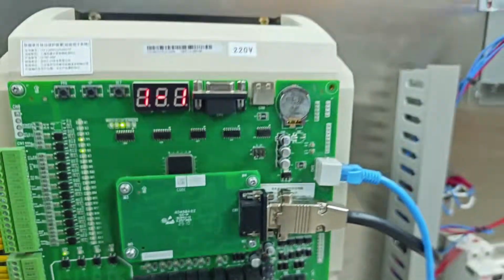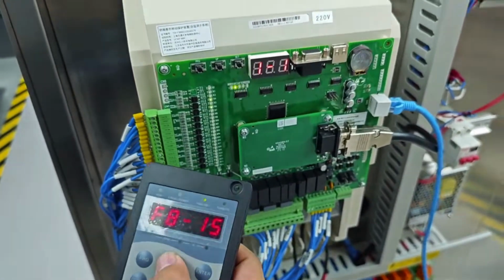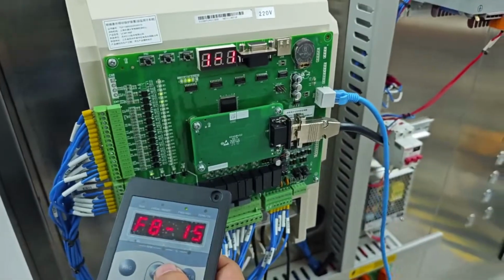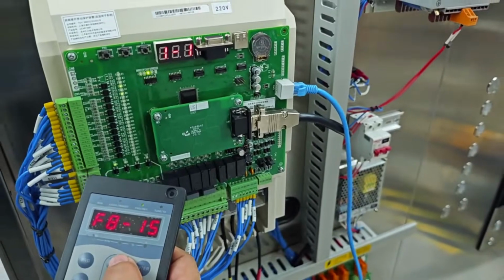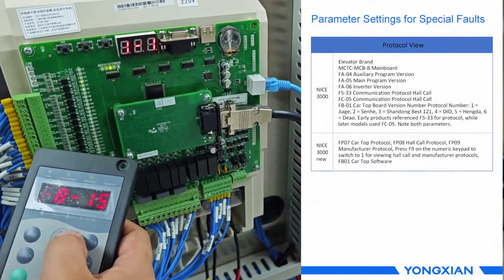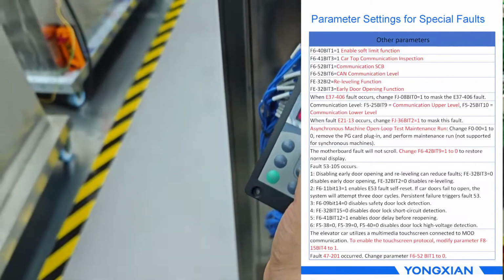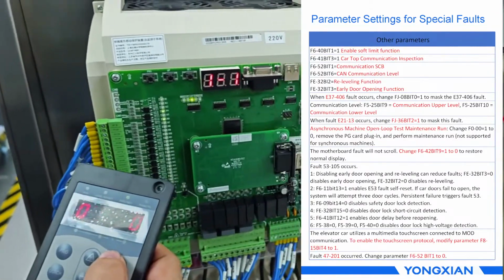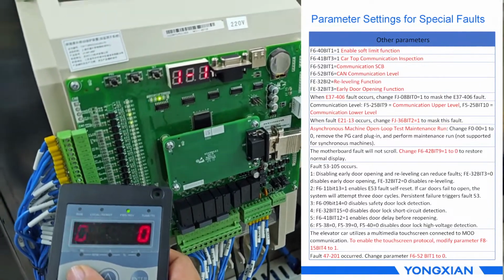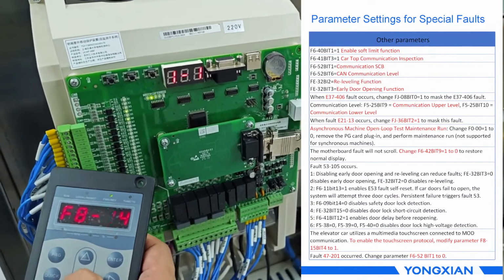If the elevator car has a multimedia touchscreen connected through Modbus communication, we can enable the touchscreen protocol by modifying parameter F8-15 bit 4 to 1, which enables the touchscreen button.